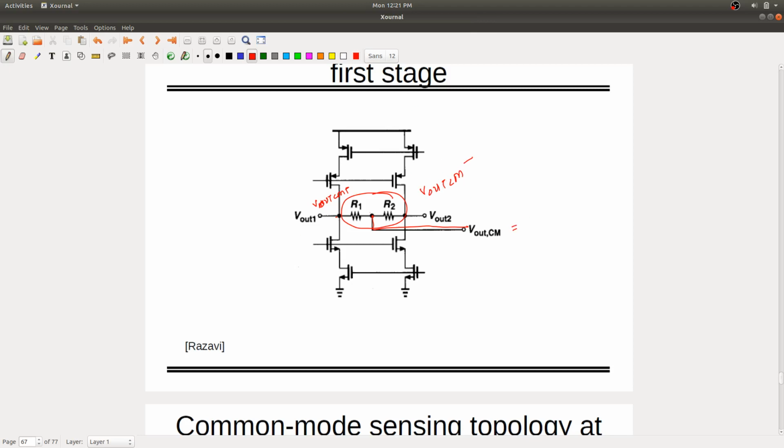So let's say this is 1.8 volt and this is 0, and this is 0.75 and this is also 0.75, because at common mode both the voltages will be equal in ideal condition, right? Because everything is the same. So common mode will have the same potential, so it will average out and it will give me 0.75. But I want how much? The V reference, I need 0.9, which will tune the required current. But this was just sensing the voltage.